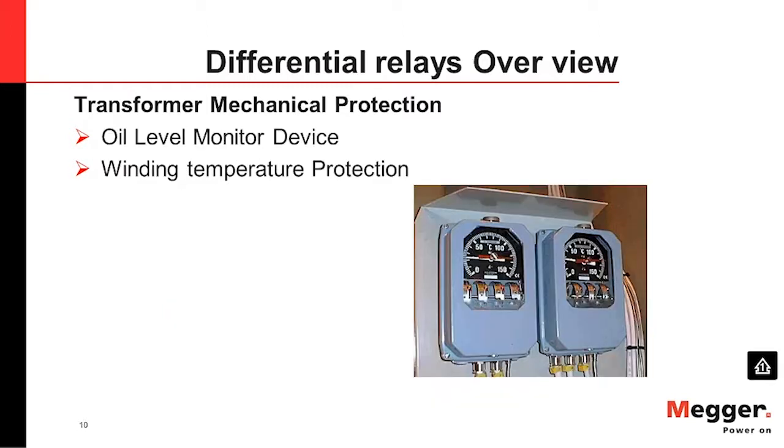Now we have some other things like the oil and the winding, and both are working together actually. So oil will always look at the oil level, and then will give you an alarm and the trip. In some cases, there is no trip if it is a monitored station. And the winding temperature actually will do 4 stages, let's say, in our case.